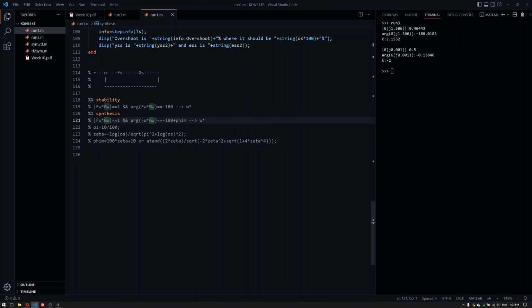And if this is a p-type controller, you can just plug in K and then work your way out. If this is a lag controller, you have seen that we have basically approximated this. We have plugged in K, brought it out, but then the other part has no gain in it, so alpha and tau are used in order to eliminate the DC gain of the lag controller, but it has an effect here.